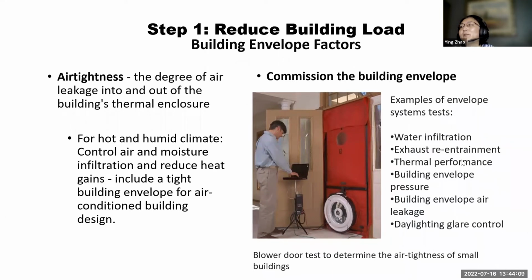For example, they will take an infrared photo to test the temperature difference of a roof or windows. If it shows some temperature is very high or low, that probably indicates a deficient area where the installation has missed something, or the insulation is broken there. So that's envelope testing.